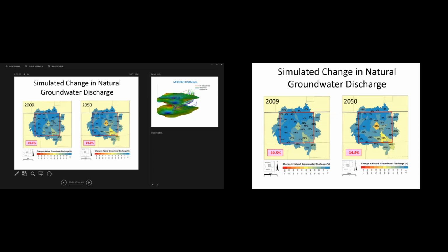People want to do it, and we've cranked out results from our model to look at how much stream flow was impacted. But it's an example where the model was, I would argue, not ready to make that assessment. There are too many issues with this. This is a steady state model. Well, it has time, it has years, but no change ever in river elevations. There's a whole thing that you do with drain cells, but that's for when we talk about boundaries. That's what I really think is going awry here.